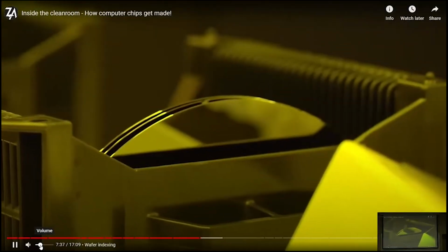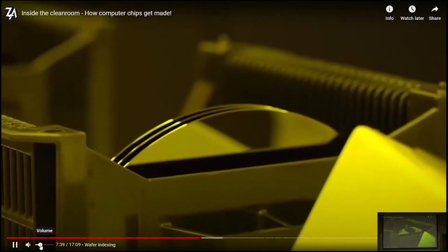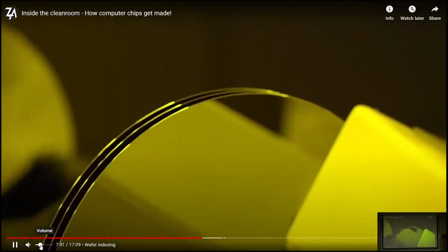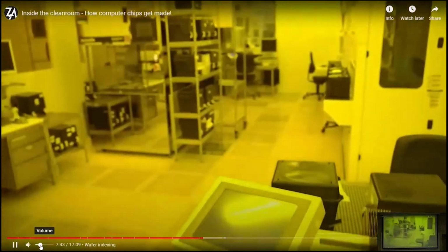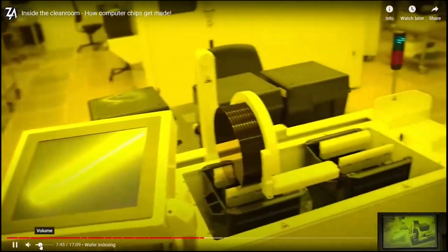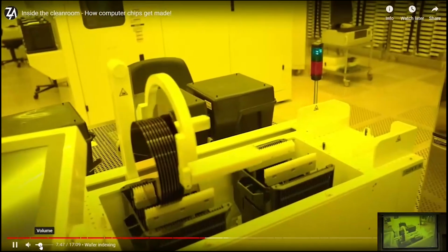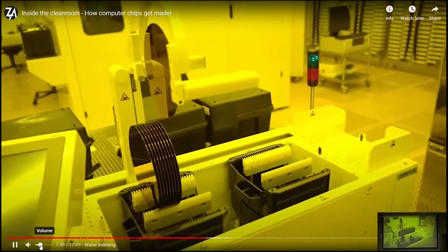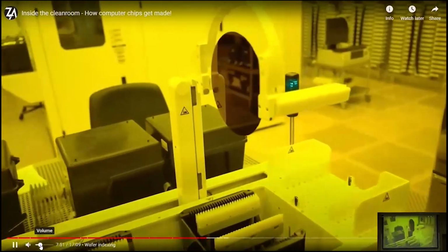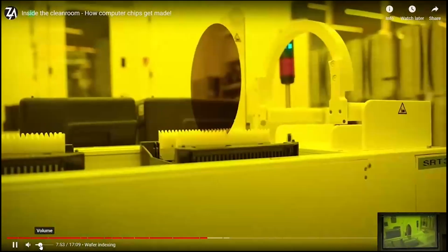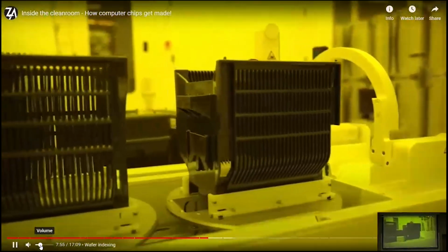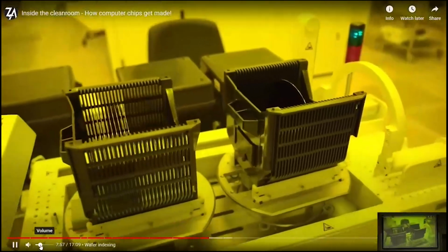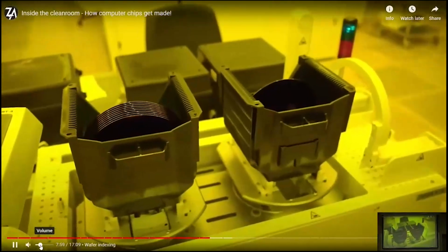So I just saw the wafers rotating. Right. Why is that? The wafers have a notch which corresponds to the wafer crystal orientation, to always align the wafer and expose or process it inside the tool in the same way. Wow. Kind of a simple system like this, just a small line, and the machine tracks it to find the notch. Yeah, exactly. Okay.